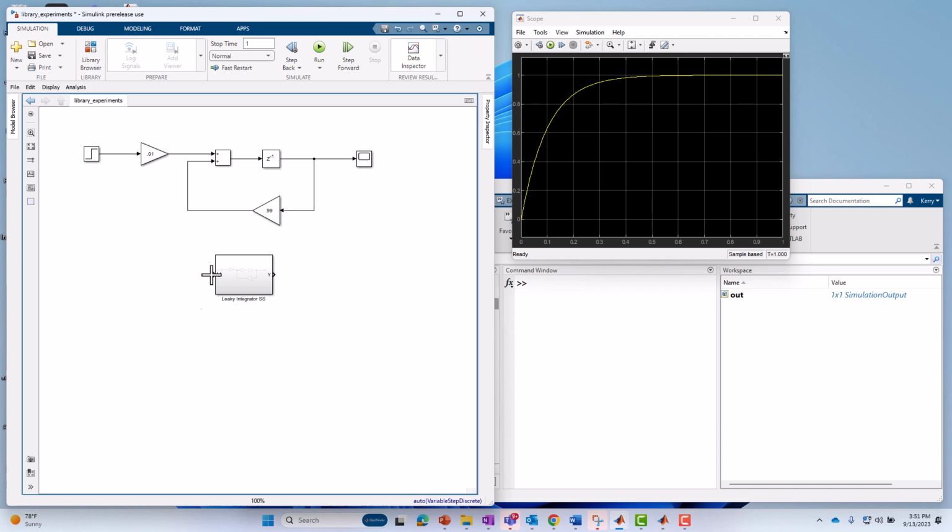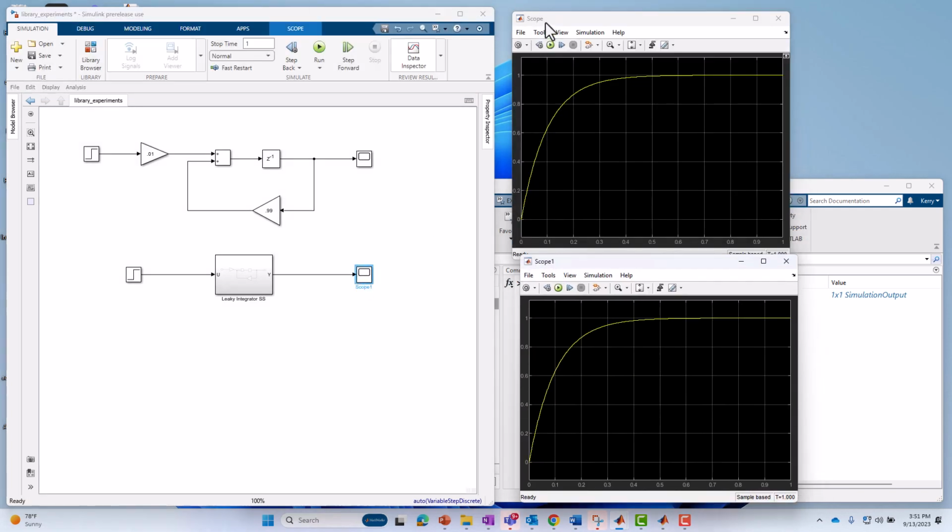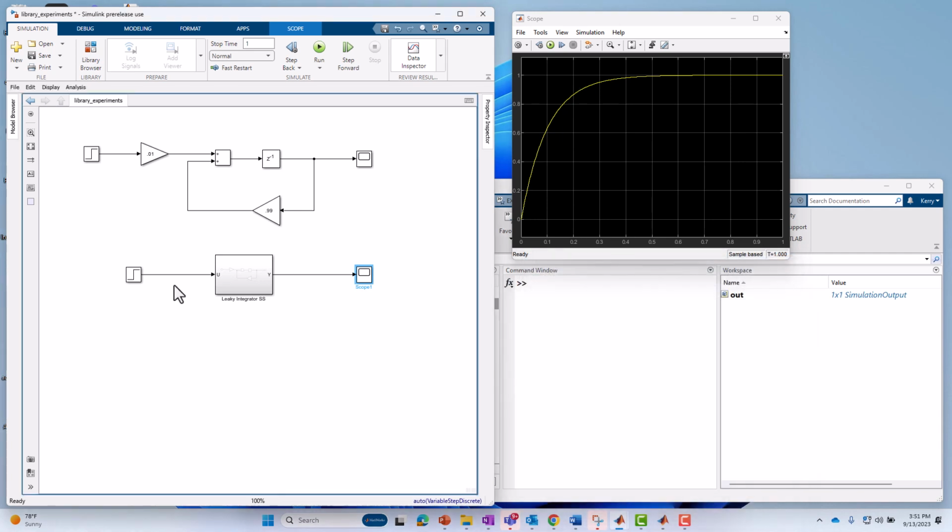Okay, we could test it the same way. We could either wire it up like this with the same input and go here, or we could put it on its own scope, either way. If I say Control Z, I'll just put another one down here. Eventually, we're not going to test all these individual variations out. We're assuming right now this just works, just to expedite things. This will be scope 1. If I pull up scope 1, you can see it looks just like scope. And of course, we could do differences and compare them, but no need to go to that trouble here. All right, so now we've gone from a flat design to some level of hierarchy in Simulink.